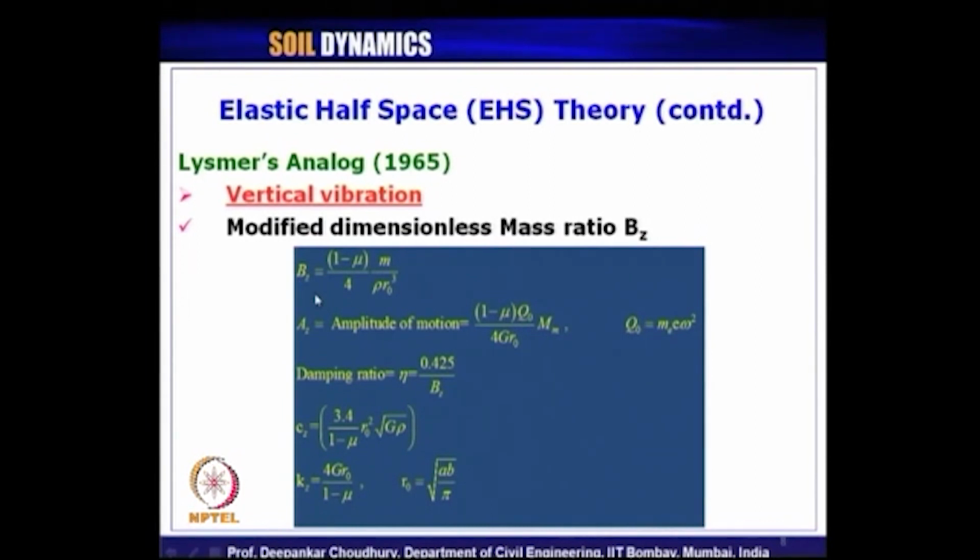Do you remember the frequency term or the Reisner's displacement functions which we have discussed just now? They are functions of two parameters, dimensionless frequency factor and Poisson's ratio. So, what is the change Lysmer did? Lysmer considered the effect of Poisson's ratio in the calculation of the non-dimensional mass ratio factor.